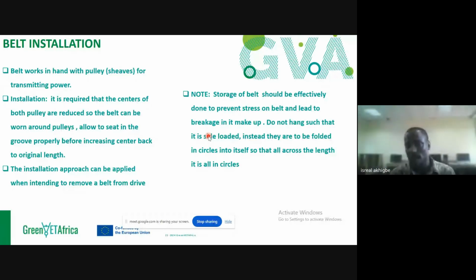You have to look at your mounting. Everybody, listen to me. Alignment. I look at balancing. We're looking at quite a number of things, but one of them is your mounting. When you are mounting your driver, remember I said your driver is a prime mover. It can be a motor, it can be an engine, it can be a steam turbine, just as long as you can get a form of